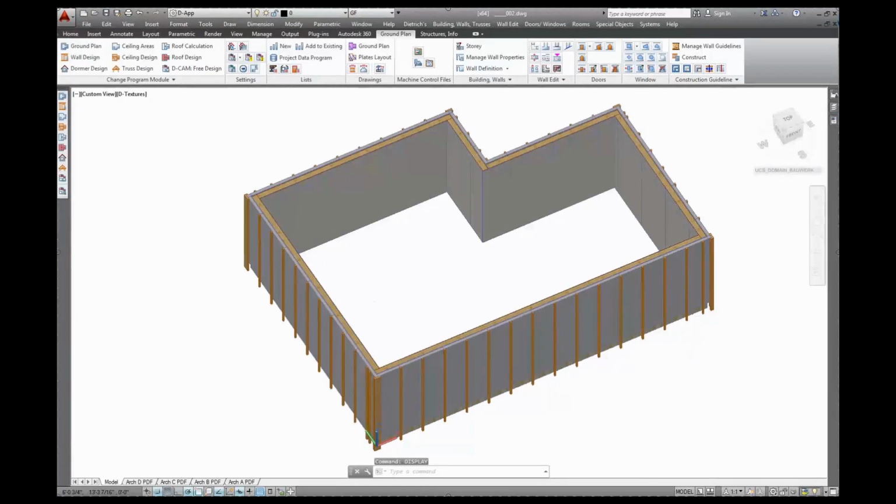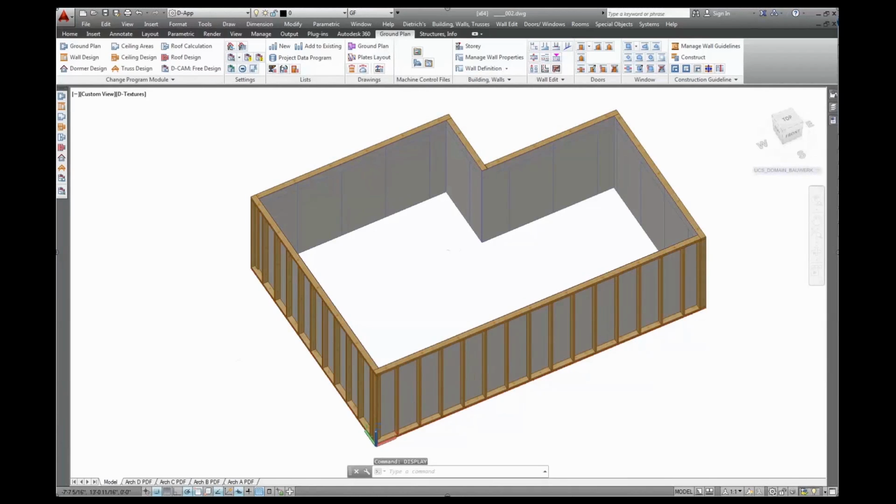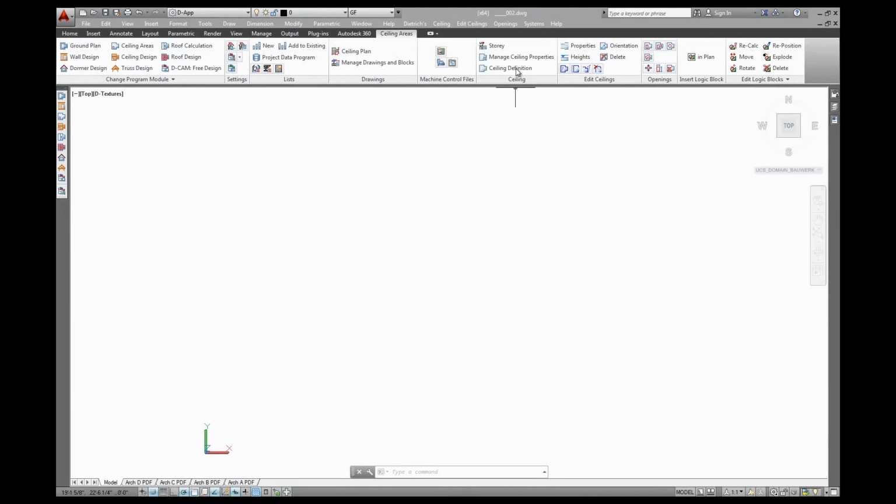If I take off the siding on the outside, that's our battens for the ventilation. Next thing would be the insulation panels. That's our EPS. Underneath is the plywood sheathing. Then most important, the actual stick frame. That's our core slice and the gypsum board on the inside. I'll tell you more about structure of the walls and how to apply that in a later chapter.